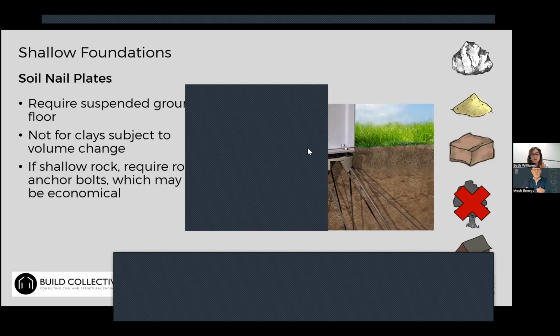Particularly with GGBS, you can swap out a significant amount of the cement, and they're the simplest like for like swaps that you can do. There's a whole question about the availability of GGBS, but from a simple perspective, those are the two ways: reduce the concrete grade where possible, and swap out the cement.